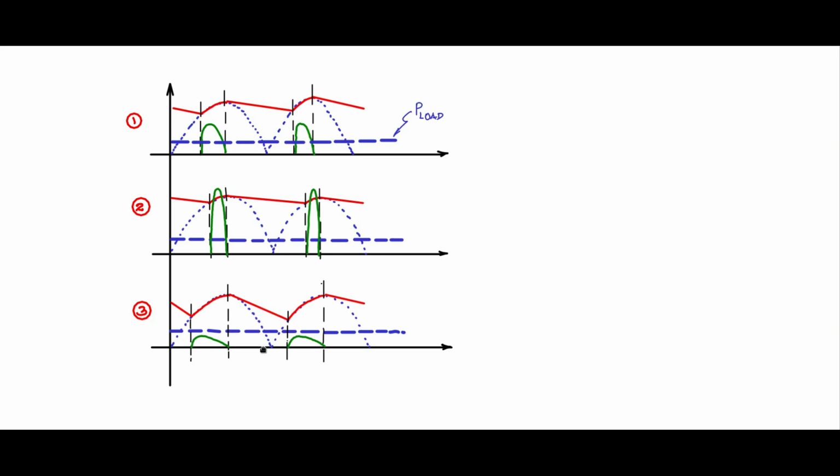I will take up an example passive power factor improvement circuit for the rectifier capacitor filter, which will give conduction for a much wider range, and probably simulate that to understand its operation. Let us now draw a passive power factor improved circuit. Now let me put this source and this diode bridge. We are familiar with this diode bridge. Then connect this source through a switch like this and across the bridge in this fashion.